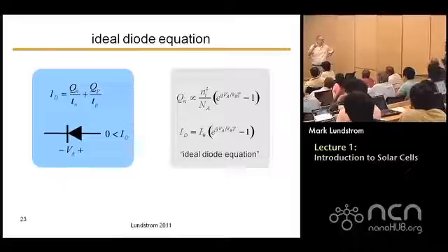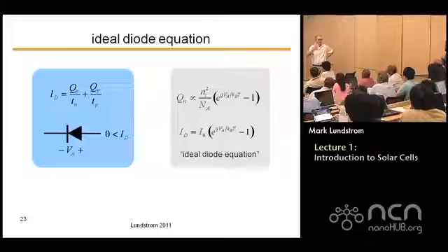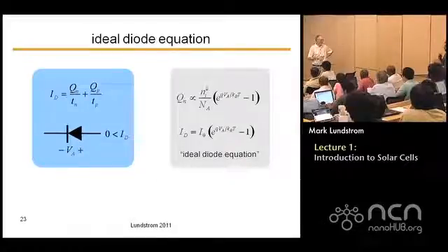So what happens is these carriers very quickly, in picoseconds or a few tenths of a picosecond, shed all of this excess energy and just relax down to the bottom of the conduction band. And generally that happens so fast that when we think about current flow, we don't even have to account for those processes when we're looking at steady state currents. They very quickly thermalize. Right. But still we will be able to collect those electrons, so we will get the electrical current.